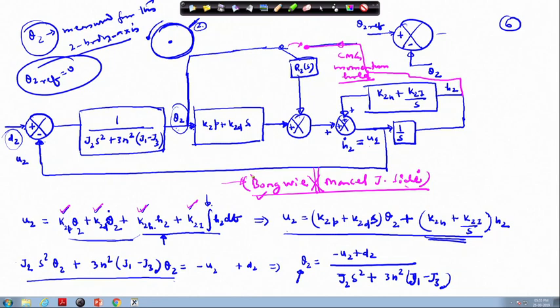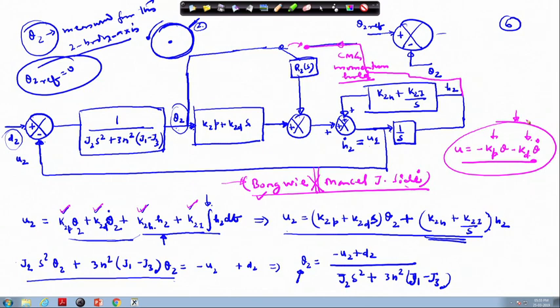So, your control input may be in the linear format, means you may be putting the control in this format, let us say k p times theta and minus k d times theta dot. So, this is just the proportional and the derivative control, but if you consider a system without linearization, that becomes your nonlinear system, and then proving the control for that, that may be tough.